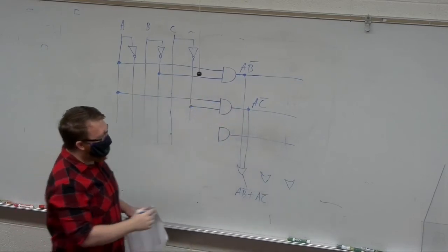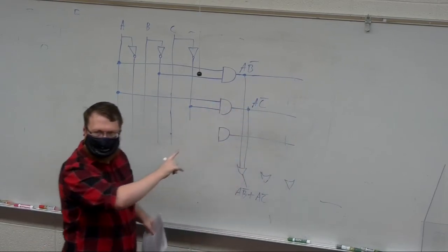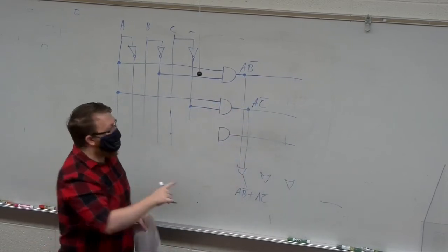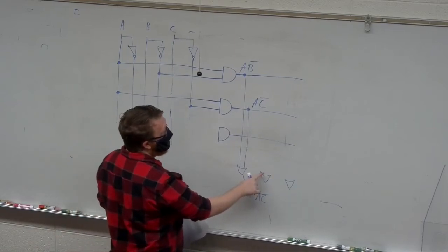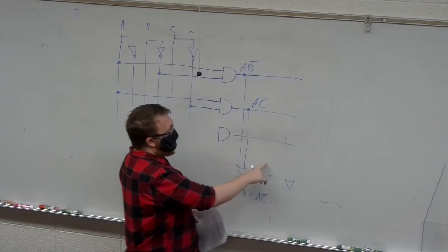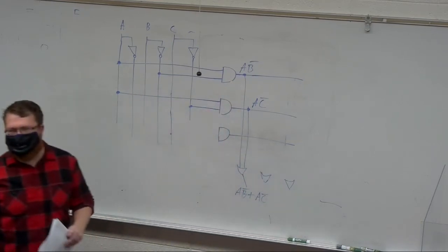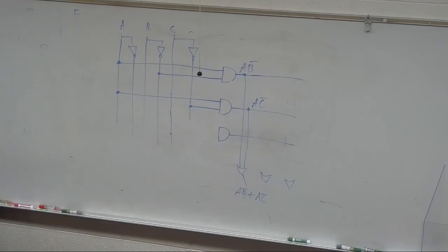What you care about is that these OR gates share these terms, right? Because if this one is AB bar and something else, I've reused this AND gate, and I don't have to repeat an AND gate. So you're going to start looking for a different type of simplification.